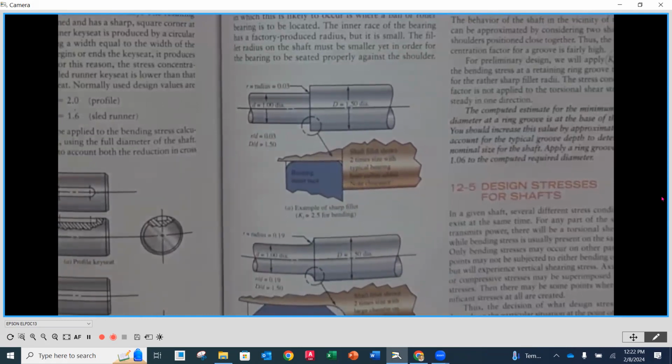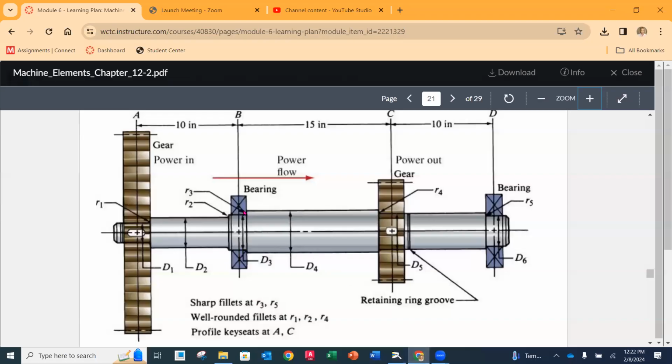Okay. So knowing where these bearings are and on what side I'm shouldering is essential. And that's at this place before we even start worrying about the diameters. So if we go back over here on the right-hand side, I've got this sharp corner. On the left-hand side, I've got a well-rounded radius, and that well-rounded radius is there because the bearing is being pressed on that bore. We don't want to press the entire length to get it to its shoulder.